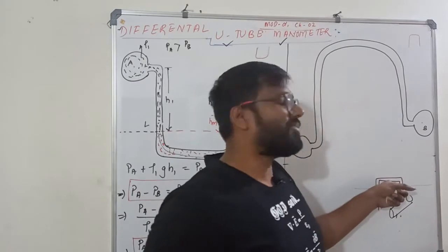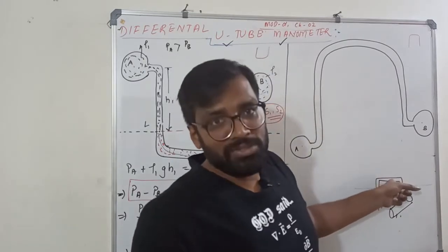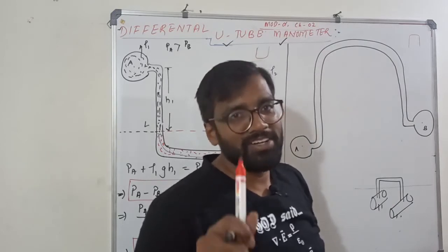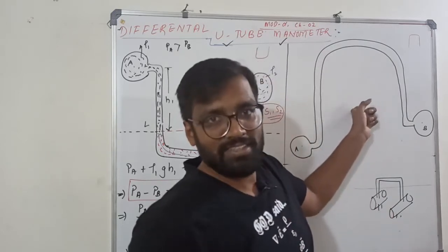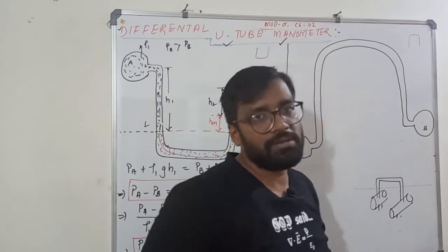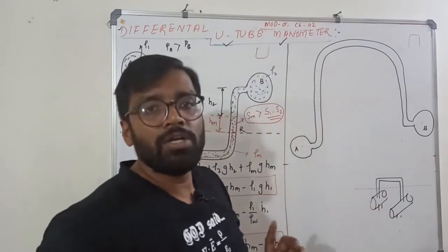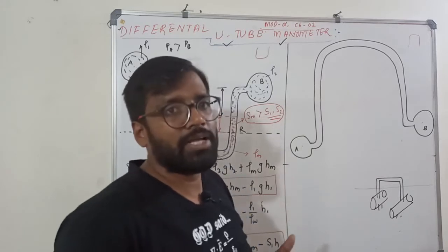Means what? What manometer are we using? U-tube inverted manometer, differential manometer. Understood the application, why we need this? U-tube inverted differential manometer. But see, it has some problem also. I can go for only low pressure measurement. I cannot go for high pressure measurement.